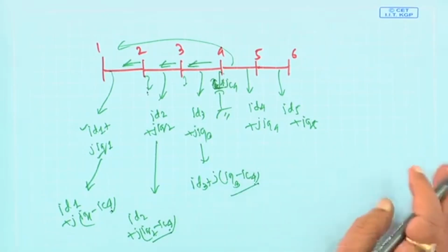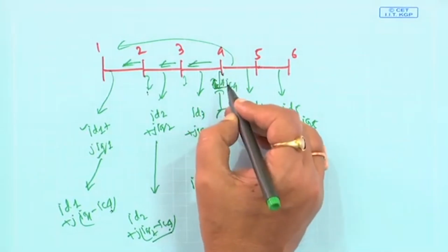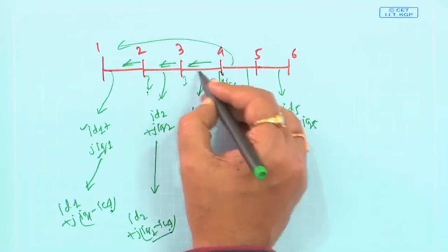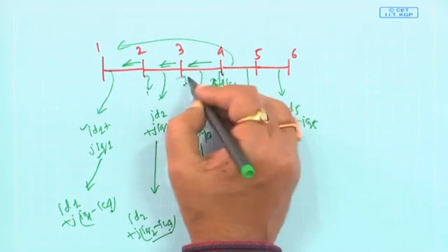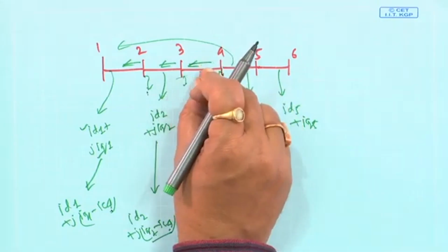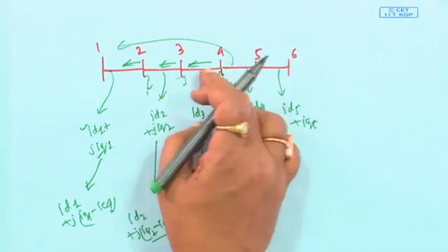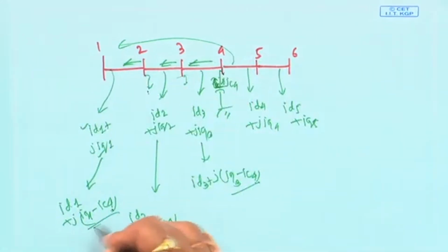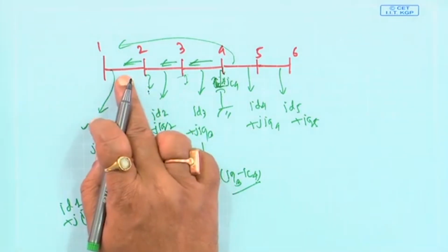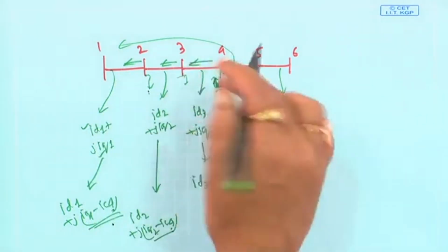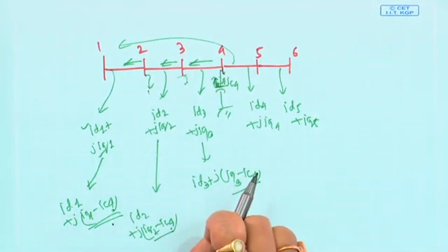That means whenever you connect a capacitor in any network, the effect is local. The branches that are very close to the capacitor connecting point, in a distribution system, will have higher loss reduction. This is a small network; in a large network, as you move toward the source, there will not be much decrease in this difference, so loss reduction will be less. But in the vicinity of the shunt capacitor connection, the loss reduction will be more.